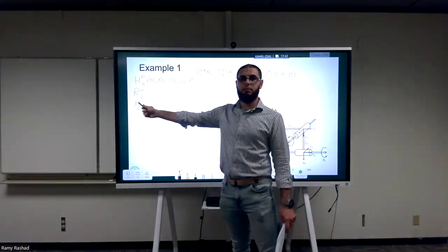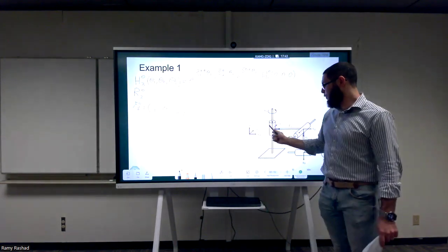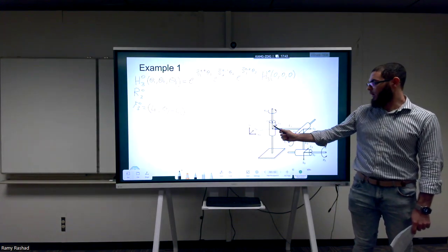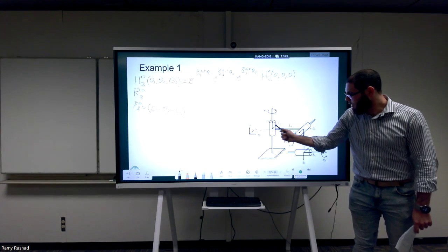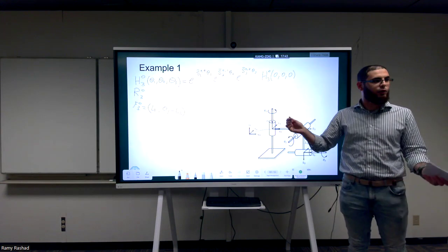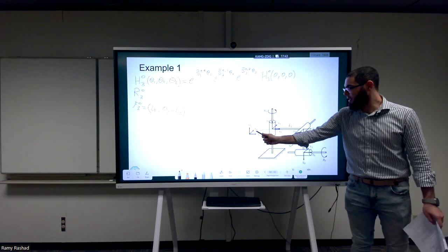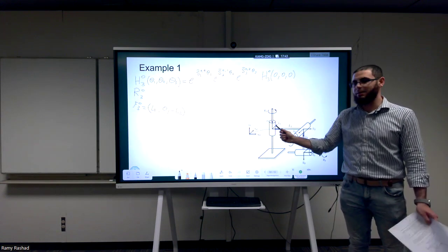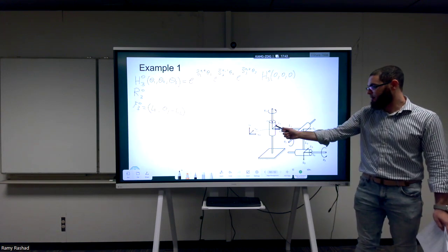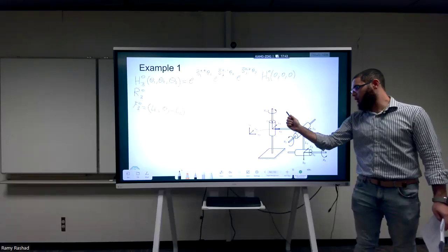Expressed in which frame? So if you're at the 0 frame, how should you move to reach this point? I move in this direction. Again, these two frames are at the same point. They are coincident; they're just drawn like this for simplicity. So frame 0 is the same as frame 1 here. I move in this direction by L1 and in this direction, which is the Y1, by 0.